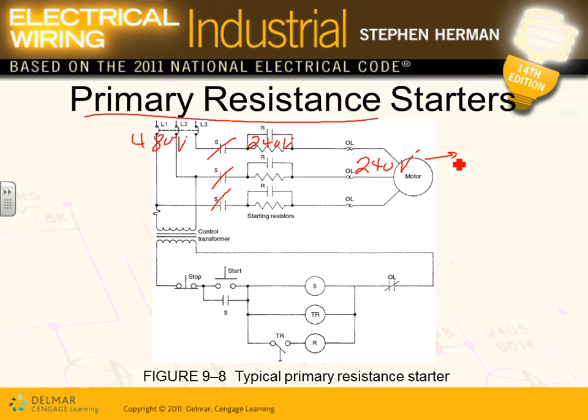By cutting the voltage by half, they cut the inrush. The inrush current will be cut down. And by cutting the inrush current, guys, they will reduce the mechanical and electrical impact on the machines. Who cares? When you start your motor, your machine's not going to jerk and bust the windings and everything else. That's called resistor starting, or voltage reduction resistor starting.